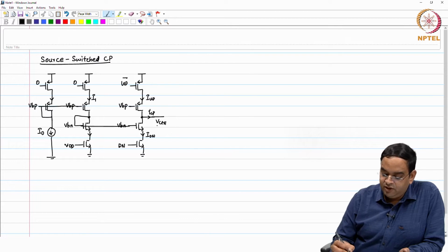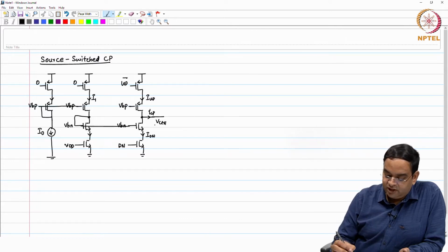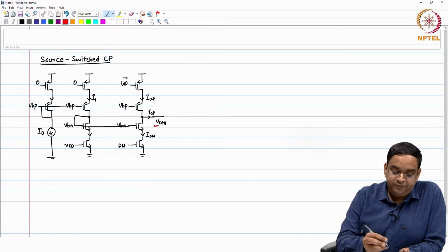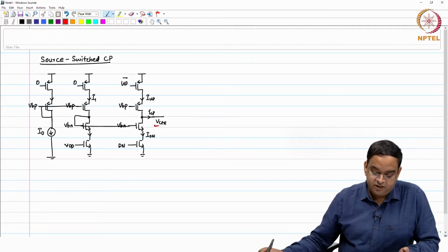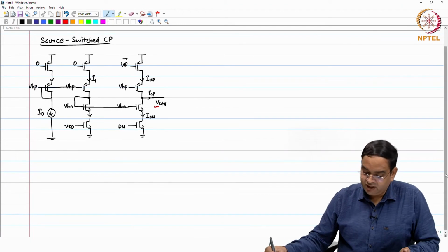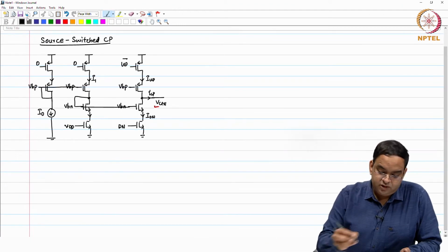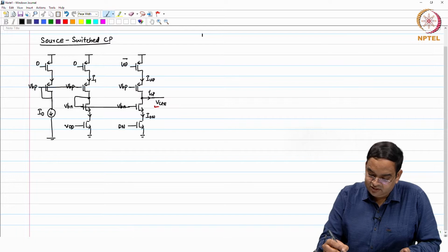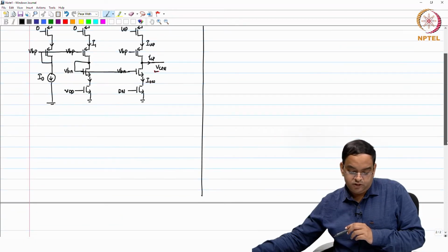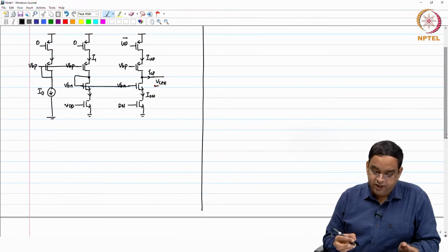And then in the actual charge pump, you have a control voltage. Because of this control voltage, you will see a mismatch between the current ICP and your I naught. Now, in order to increase the matching or reduce this mismatch, we can have a cascoded current source that will have lesser susceptibility towards V control. So, what I can do is the following.